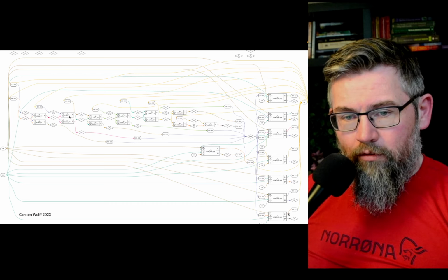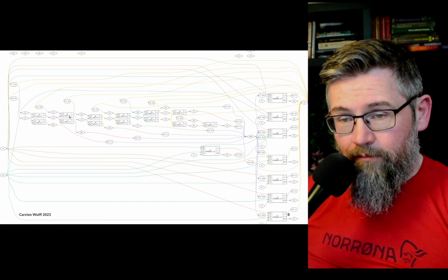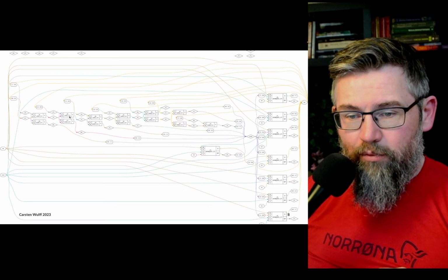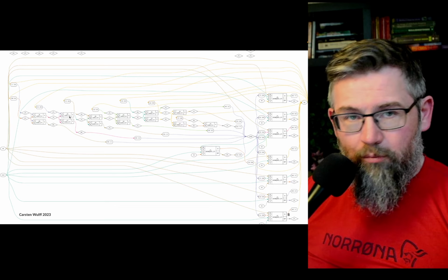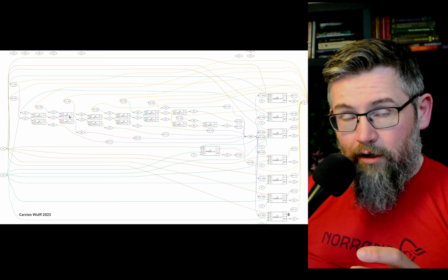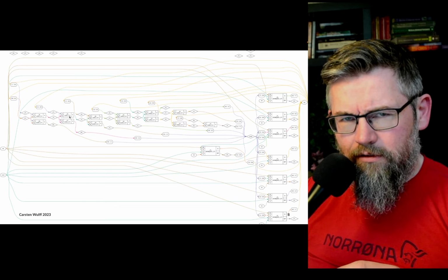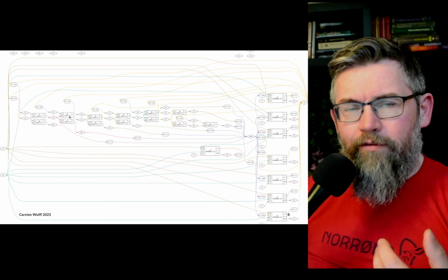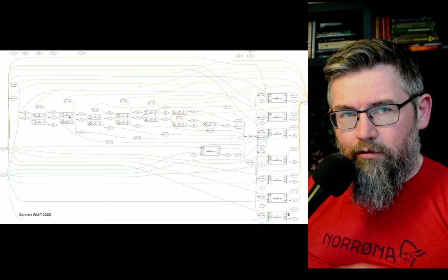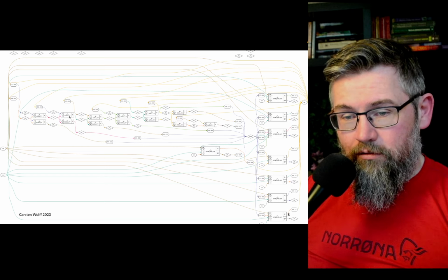So an important part of the timing step is to actually add real timing. So we've used SPICE simulators to compute how long it takes from the A input of the AND changing to the Y output changing. And we store that in the Liberty file. And then also after layout, we have to introduce parasitics, both resistance and capacitance, mostly capacitance though, to modify those delays, which means that in digital we also need to do netlist simulation, or simulation at the level of the actual design, to see that it still works.